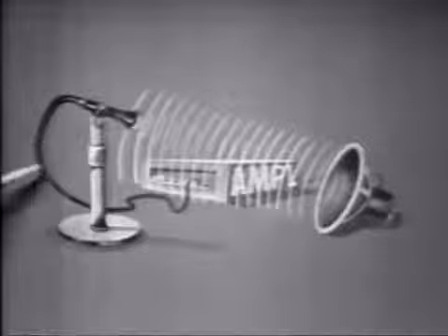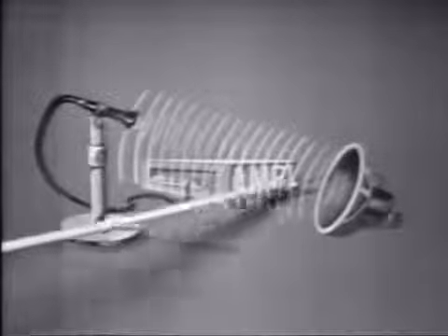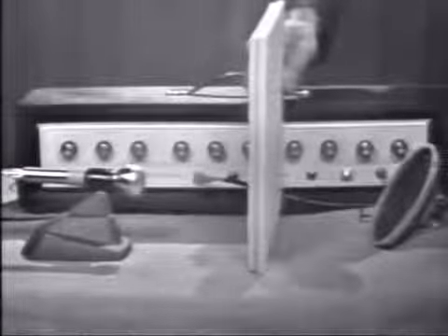Any sound picked up by the microphone is fed through the amplifier and out the speaker as sound. If the microphone picks up the sound coming out of the speaker, the output is feeding the input and the stage oscillates. Now, since there's no way to control the amount of feedback, the strength of the oscillator signal continues to increase. You can hear this increase when we remove the tiles slowly and allow the microphone to pick up the speaker's output.